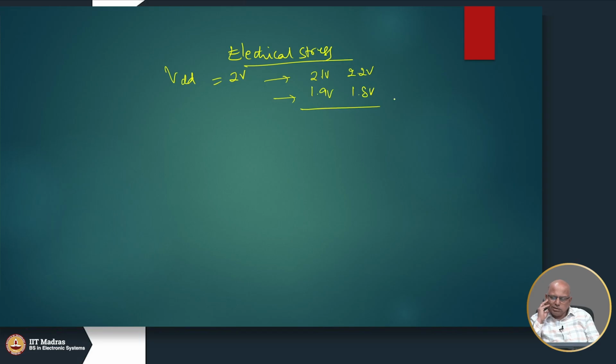So, when you reduce the voltage, the delays will go up. When you increase the voltage, stress mechanisms will set in. So, typically voltage stress is actually this, increasing the voltage, that kicks in a lot of failure mechanisms. Sometimes they will do it in a range. They will say we will go from 1.9 volts to 2.2 volts. So, they will apply all voltages between 1.9 to 2.2, and they may do it only for a sample of devices.